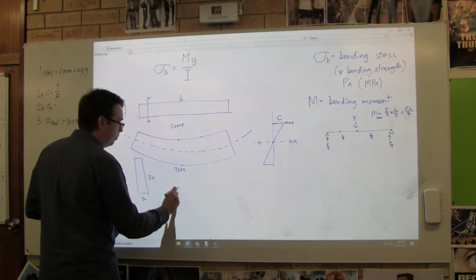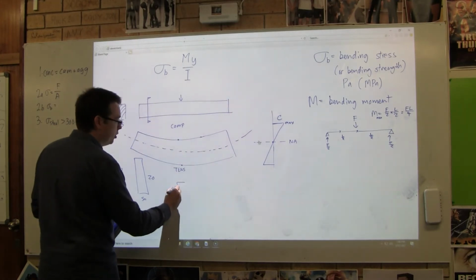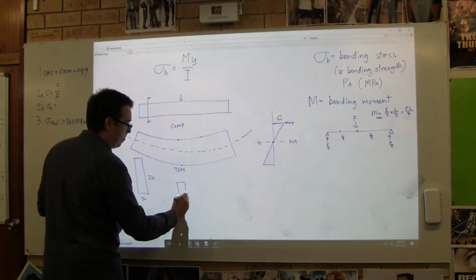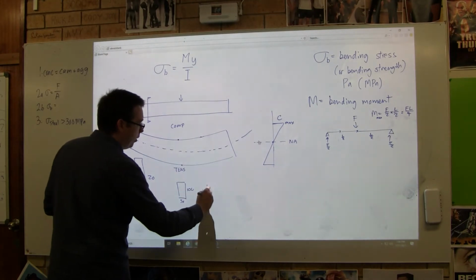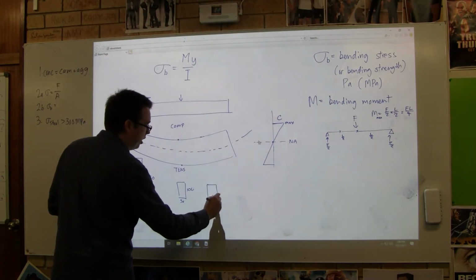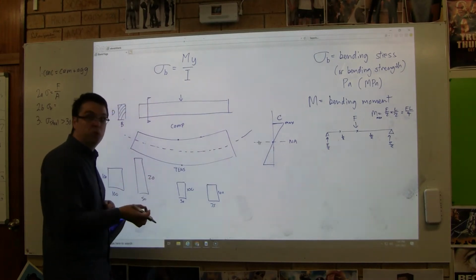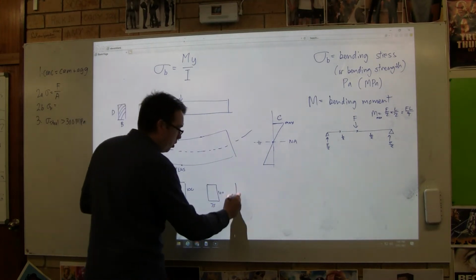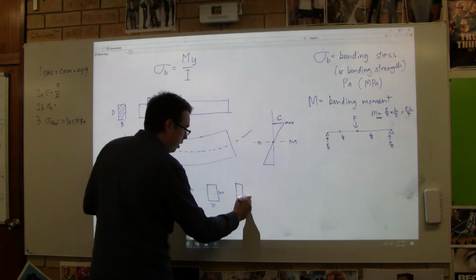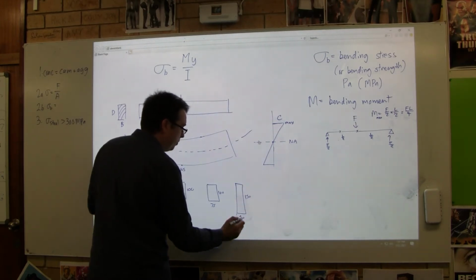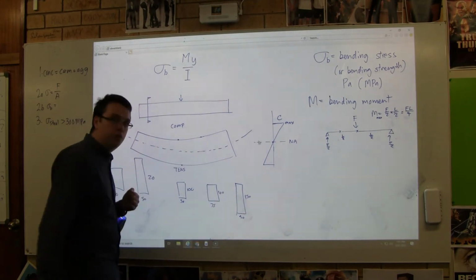Now, for instance, a floor joist is usually 50 by 100. And then a bearer is usually a little bit wider, 75 by 100. But what I've done is I've just added an extra 50% of the wood. If I instead had gone this way, 150 by 50, that one would be better for bending.